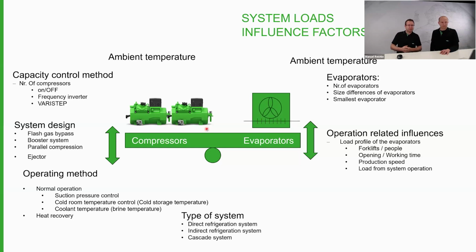The system design itself has also quite an influence on the compressors. If it's a flash gas bypass system, the MT compressor have to deal with the evaporator mass flow plus the flash gas mass flow. So they have to balance the changing requests by the high pressure, but also by the suction pressure. If it's a booster system, the LT stage has an influence. If this is bringing more capacity inside or less, it can be seen as an additional evaporator, but it's bringing also, let's say, the scale into a movement.